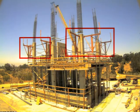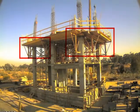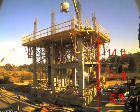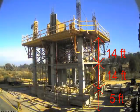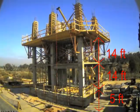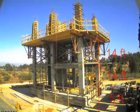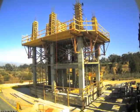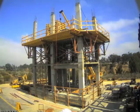During construction of structures higher than 1 story, safety measures in the form of scaffolding must be provided for workers. In accordance with the Occupational Safety and Health Administration, known as OSHA, scaffolds at least 18 inches wide must be provided as a walkway for workers, and they should be at least 10 feet away from power lines. Scaffolds must remain completely planked platforms, equipped with safety guardrails on all open sides, and be tied properly to the building. If a scaffold is more than 10 feet above ground, workers must have fall protection. For construction of this multi-story building, all the workers were provided with safety training and fall protection. In addition, all required OSHA regulations and codes were adhered to.